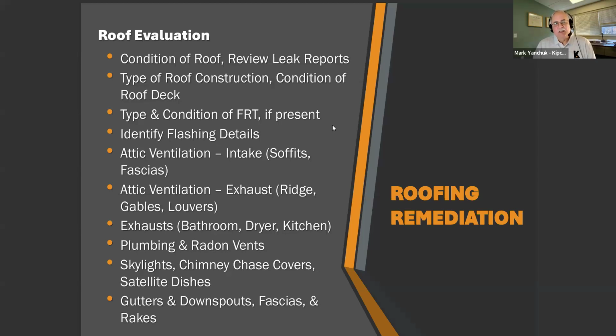But it doesn't stop right there. So right there, you're talking about the roof and the roof construction, but there's more to a roofing project. There's the attic ventilation. So you've got to see what kind of system is being used for the attic ventilation. Usually the intake air is coming in from the soffits or fascias or lower down on the roof. And it may be handled in a variety of different ways. And also with the attic ventilation, you have to look at where it is being exhausted. Usually it's maybe a ridge vent, maybe there are gable vents, maybe there are static louvers up on the roof.